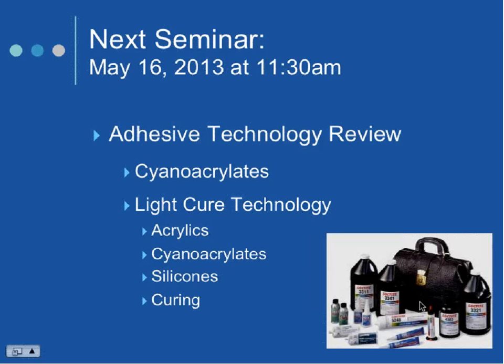It depends on the adhesive. If it's a cyanoacrylate, I would say the day it expires, get rid of it, because they go bad very quickly. You can usually see it, but the strength will drop off and everything will go south very quickly because they're very sensitive to moisture and being refrigerated. Acrylics, I've seen them last well over a year. I've seen them last 2 years.